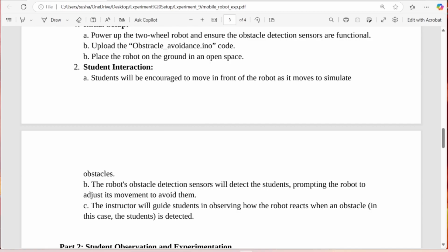Now, in the case of a line following robot, at the rear side of the robot, there are infrared sensors. These infrared sensors can sense light. So when it is following a black line, for example, 3 of the sensors are going to sense the surface condition. If there's a black line, one of the sensors will show white, then black, then white. In terms of the signal, it could be 101 or 010. And basically by following that, the robot can actually follow the line.